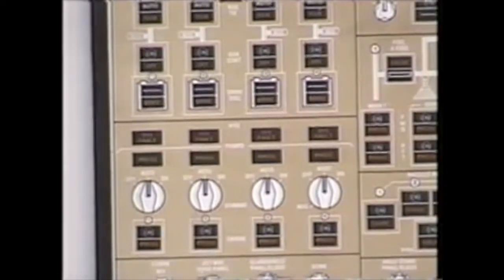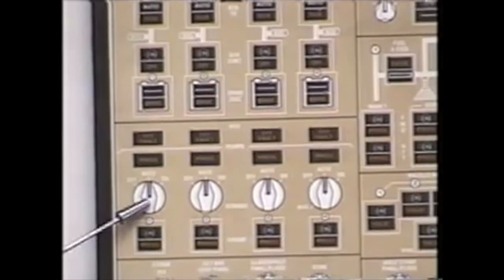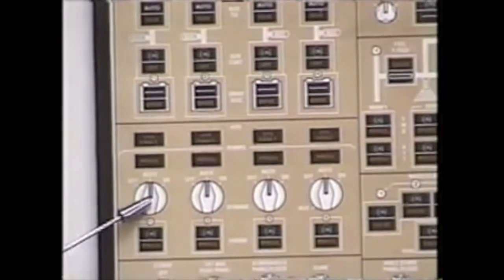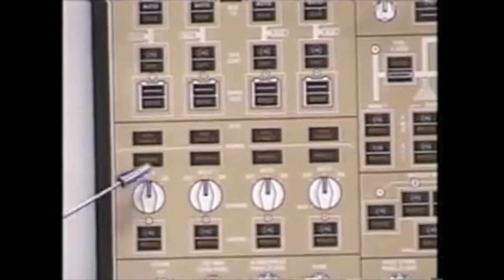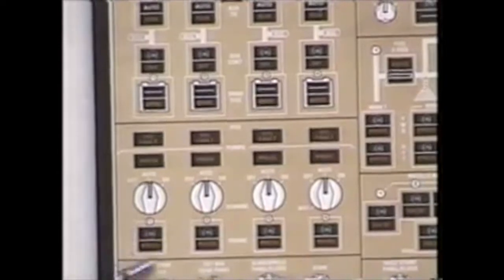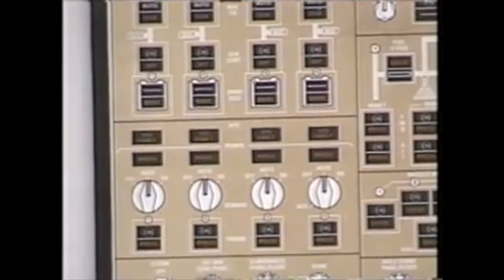If we pull the fire switch for that engine, that will shut off the fluid supply to the EDP and not the ADP. As a result, the hydraulic system will still operate. The air demand pump takes pneumatic air from another point of your airplane, not the engine. It will pressurize the system. The fluid supply is shut off to the EDP. As a result, the pump is not putting out pressure, and it is no longer getting lubrication for cooling. However, if the engine is windmilling, the EDP is still turning.